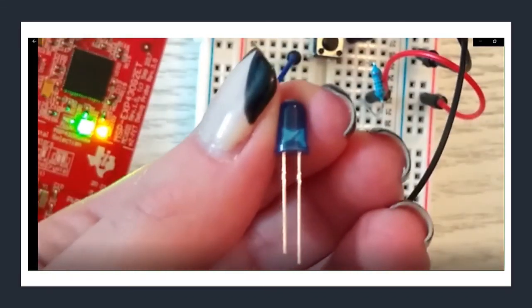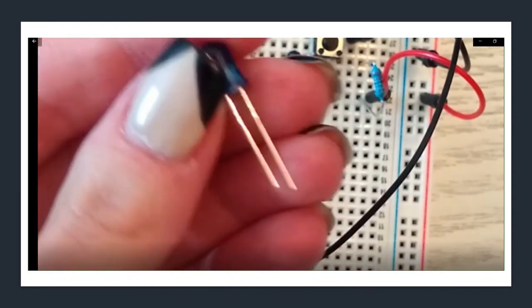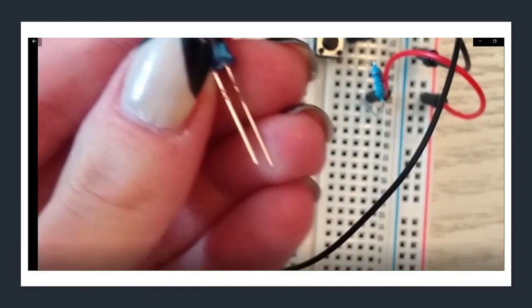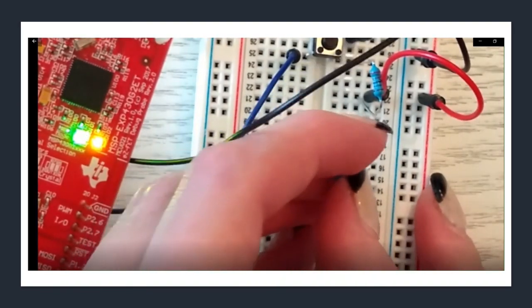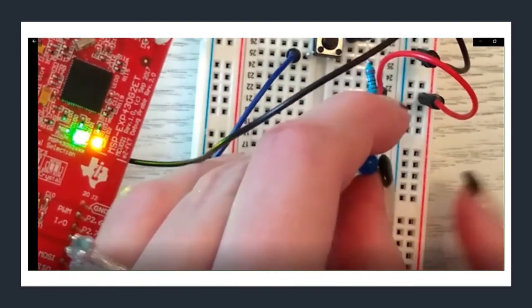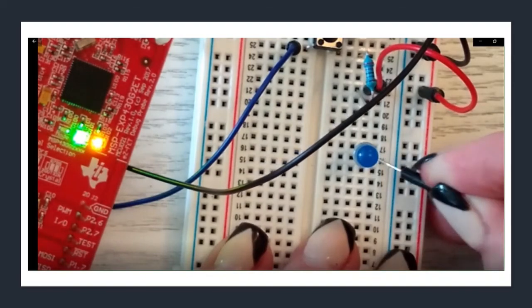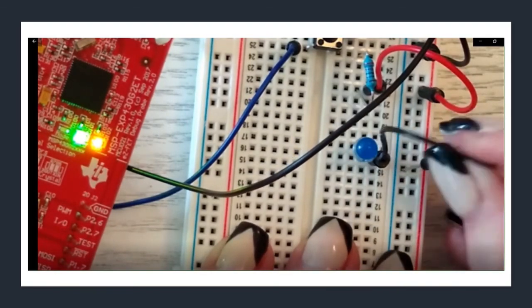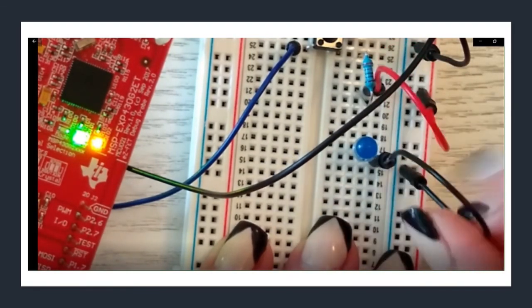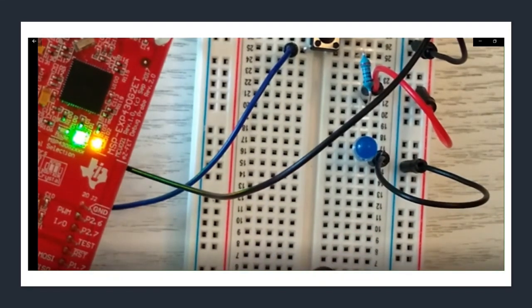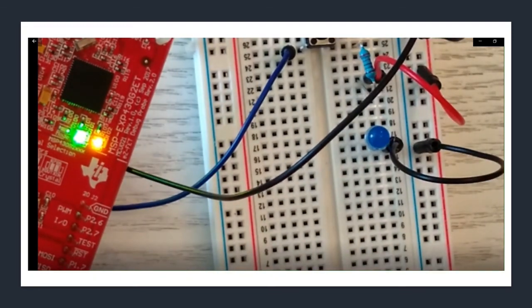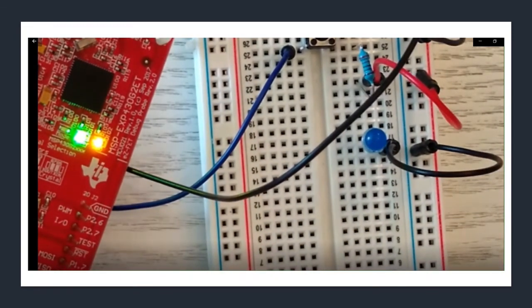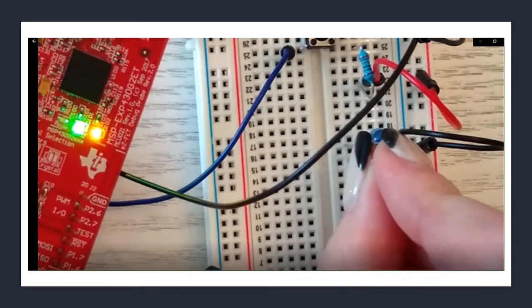Okay, now I'm going to add an LED to my board, and if you'll remember, the short side we connect to the ground. So remember, short side, negative, we ground that. I'll span it between two different rows. The short side I'll go ahead and add to my ground rail. And the long side, I will not directly connect to anything before I add a resistor. So you always want to add a resistor in to your LED.